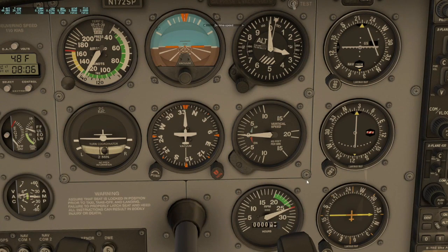Here we go. Now the needle is starting to move to the center, and at that point I'm going to turn to 025 in order to intercept my inbound radial of 250. So I'm here now. I'm almost coming to this radial. I'm going to now turn to come this way and intercept and go inbound.